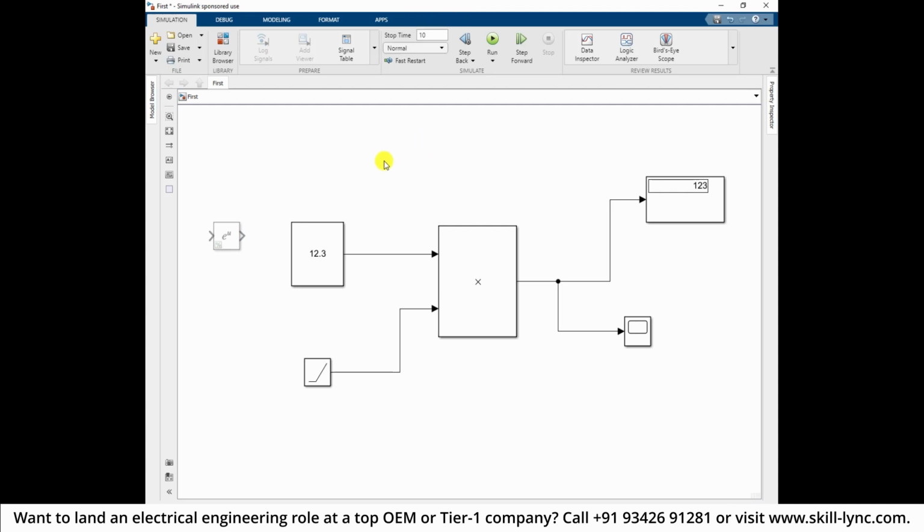Simulink also helps us create some text which is relevant to this model and which is not going to be executed, like this block which is commented out. We can make some annotations as well. If I double click anywhere, instead of searching for any block, and click on create annotation, it will ask me to type any text.